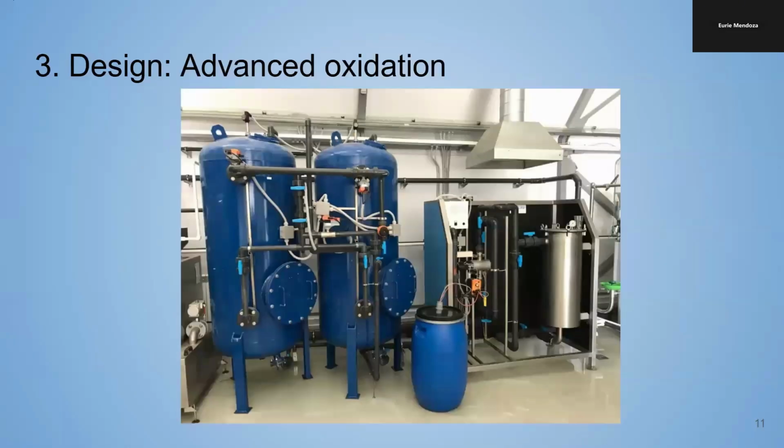The use of UV light is a common method for disinfecting water, but it does face limitations. Advanced oxidation is a technique that can be combined with UV light disinfection. It generates hydroxyl radicals, which are highly reactive molecules that make it a potent oxidizing agent. Advanced oxidation not only disinfects water, but also provides a 6-log removal of microorganisms and a 0.5 log removal of 1,4-dioxane.